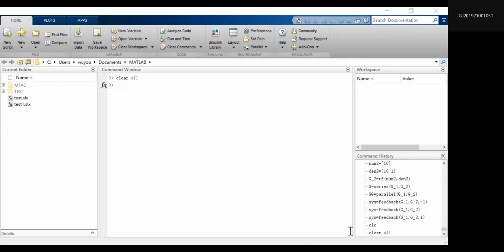see here, a continuous system is a curve, right? But in a computer system it becomes discrete. It will do the sampling at each interval, and this interval is called sample time. And how can a continuous system become discrete? The system will take the value at each interval.